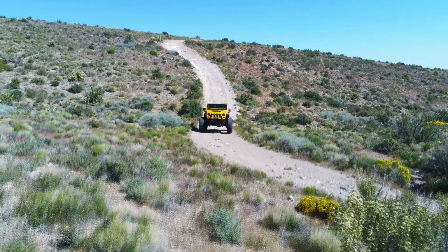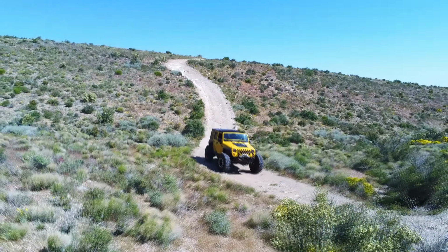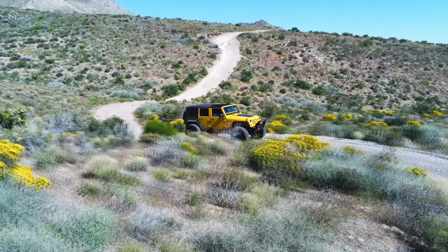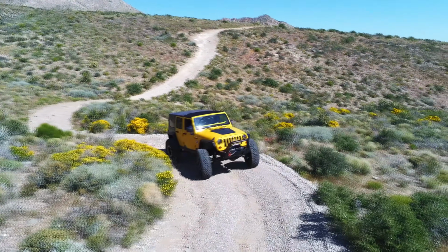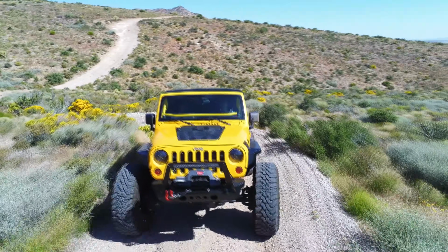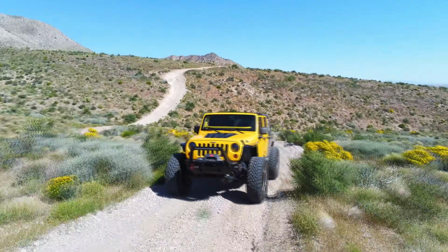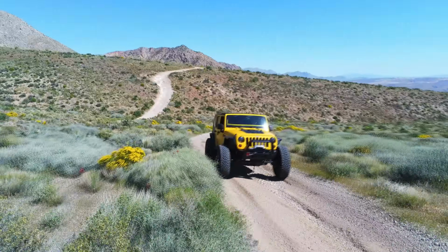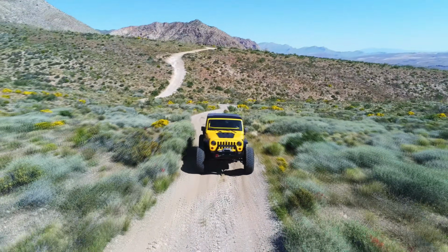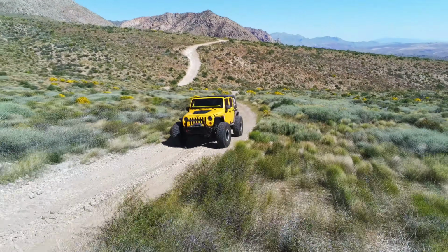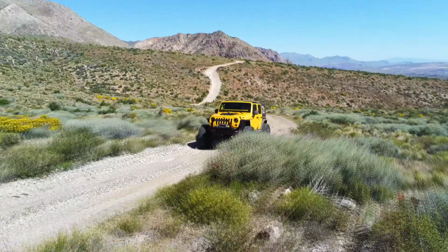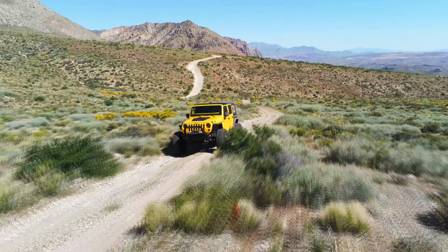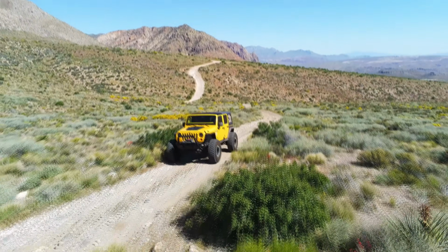But if you're cruising down the highway just on the border of open loop and closed loop, it's really easy to just slow down a little bit, kick it back into closed loop, and then enjoy the benefits of that extra economy. So what I suggest you do, it doesn't really matter if you're running a scan gauge like this Aeroforce Interceptor, or if you're using a Bluetooth adapter with an app, or even a full-blown scanner. Just get something that will indicate the difference between closed loop and open loop, and you can save yourself a lot of money in fuel.